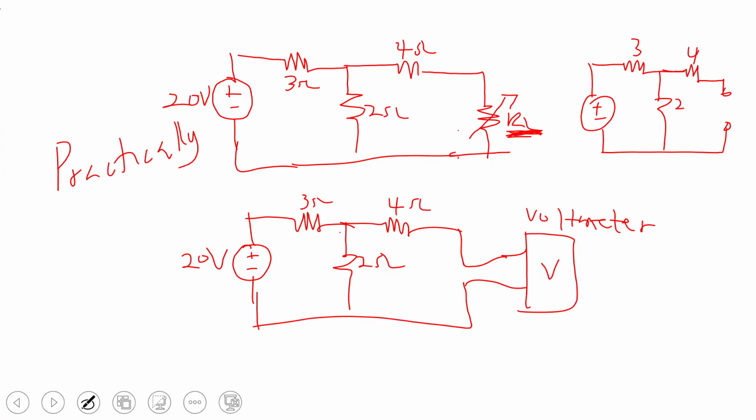If you were supposed to do this practically, Thevenin's theorem would have been very short. All he's saying is that for the element whose current or voltage you want to find, first remove the element. Then go and bring a voltmeter and measure the voltage at the terminal A, B. Come and measure that voltage, and call it the Thevenin's voltage.